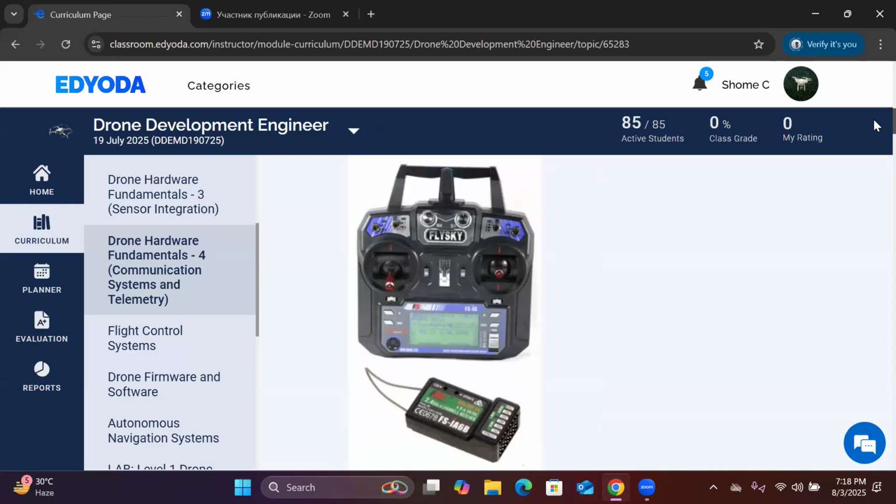Usually for a sophisticated drone, like for defense applications, the system integration part or the overall console looks different. There the ground control station or the com box is opaque in nature, so there is no display directly attached to the communication box. From the communication box, through the LAN cable or RJ45 connectivity, the communication is fed to some other UI console. I have used a platform from GETAC.